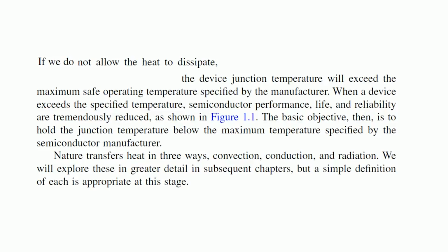specified by the manufacturer. For simplicity's sake, right now I will ignore transients and only talk of it as if it is steady state, because transients are slightly different. In transients, because of the dV/dt and dI/dt, other failures can happen, though you may be in the safe operating area. When a device exceeds the specified temperature, semiconductor performance, life and reliability are reduced.